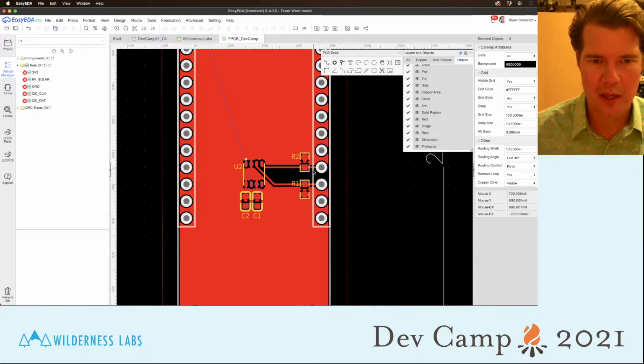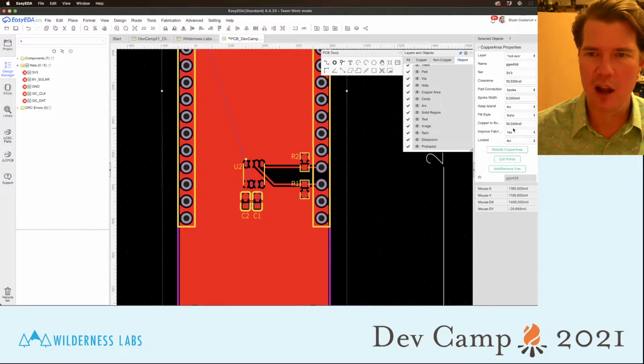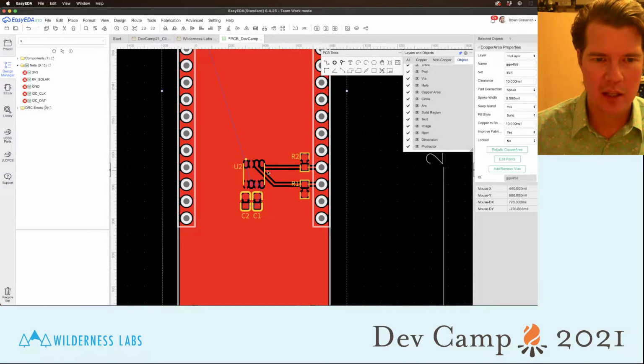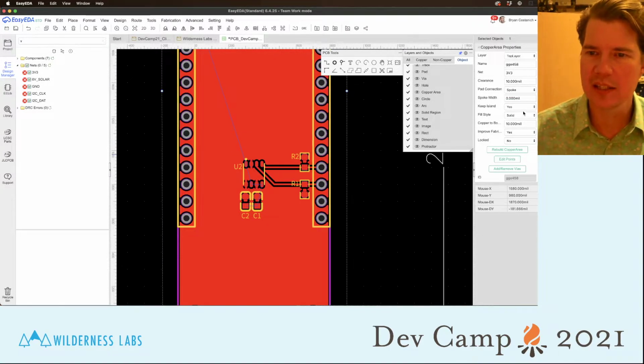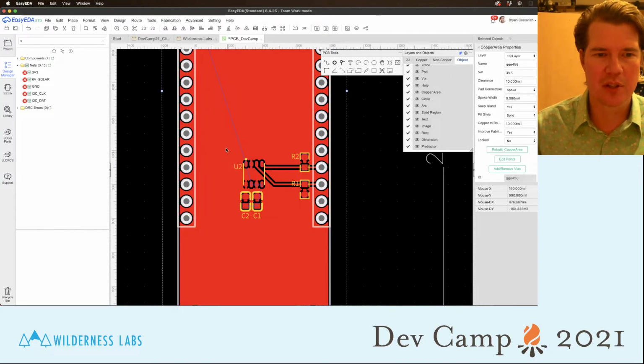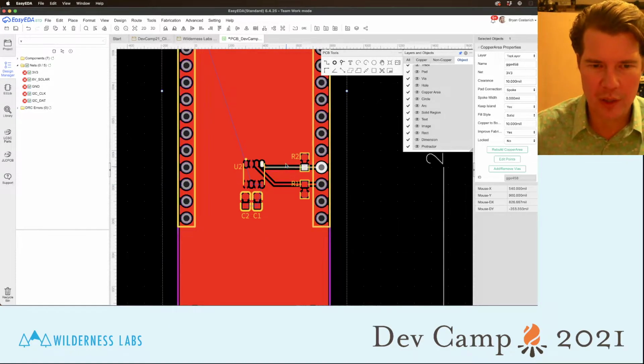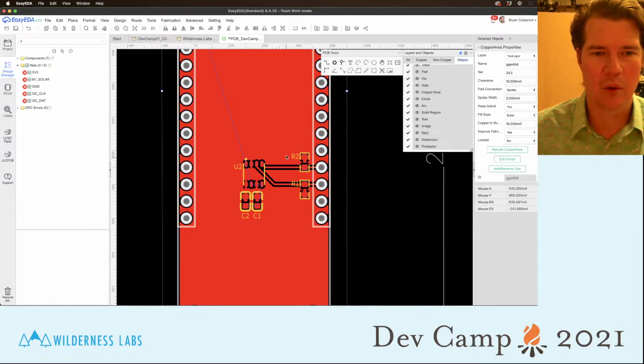That will rebuild. And this brings up one additional thing, which is on this copper area, you have an option for keep island, yes or no. An island is an unconnected area of a pour. That looks nice, but when you're doing complex boards, sometimes you'll see a rat line between two things that are 3 volt 3, and you're like, I don't understand, why is that not connected?